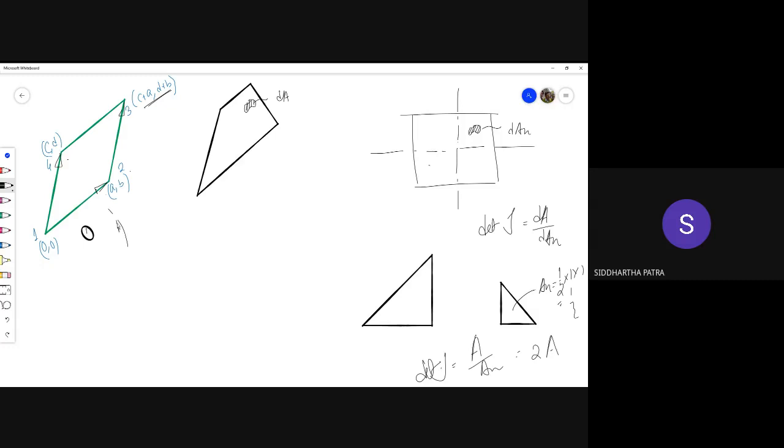Now this is a general parallelogram. No, I don't need the expression. But tell me, is it still a function of xi and eta? No, sir. So you see this A, B, C and D, these are still arbitrary values. But just by taking a parallelogram geometry, we have been able to make the Jacobian a matrix of constants. Now a parallelogram itself stands for all of these geometries: a square, a rectangle, a rhombus maybe,